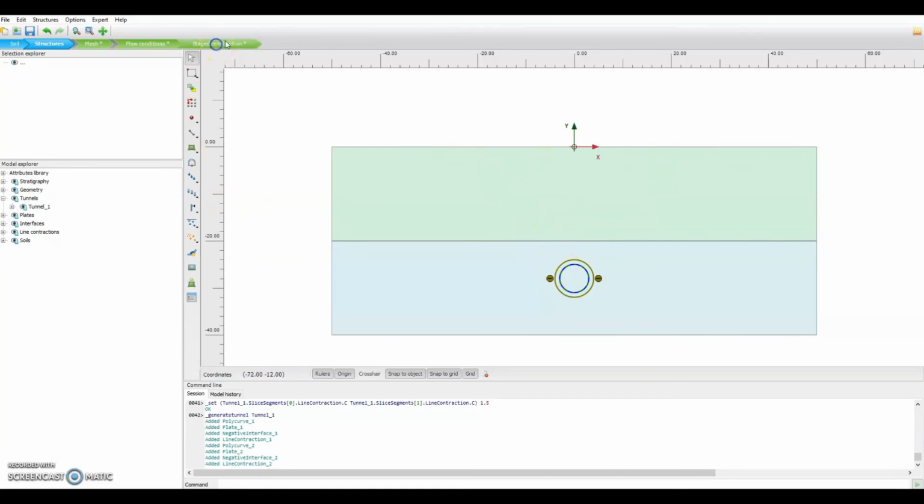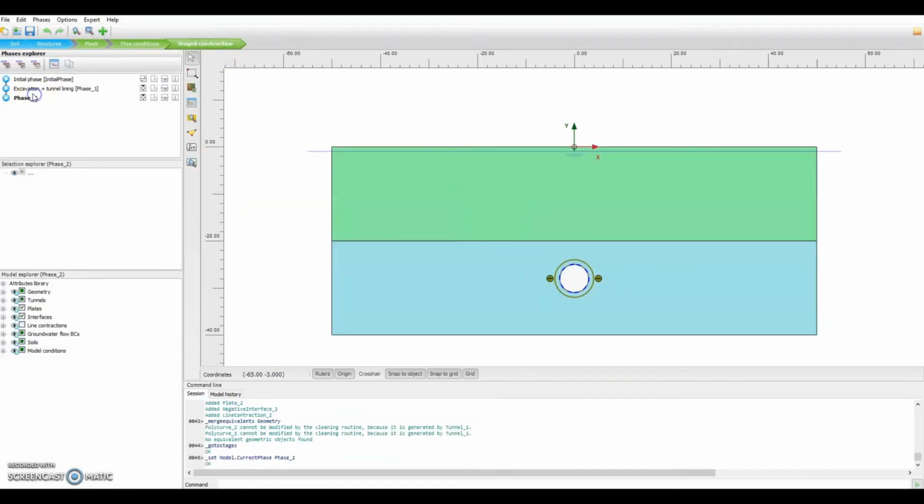And what that actually means is that when the TBM is excavating this tunnel in here, it's not going to be perfect. You're going to have a slight amount of over excavation beyond the profile of the tunnel, which you're going to fill with grout, but it's still not going to be perfect. So you end up having a slight amount of soil being lost than you actually need to.